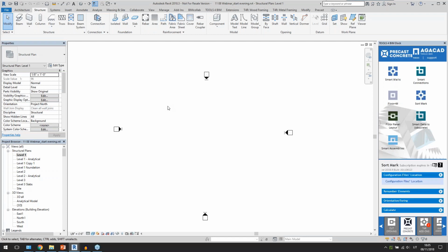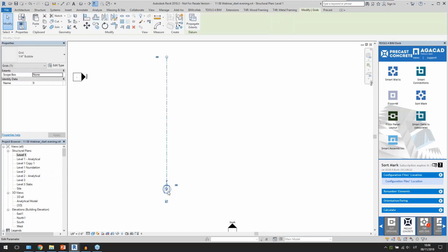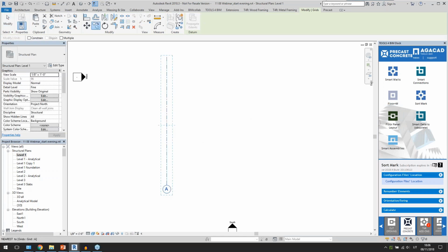So how do you create a precast building? It depends on what information you have. But basically, there are tools for architects, structural engineers, and system engineers in Revit, so you can do all the parts in one model. For structural guys, we have different commands for beams, columns, floors, foundations, and rebars. But first of all, probably we need to create grid lines. You select the type of the grid, and then you draw where the grid of your building is. You give the name for the grid.